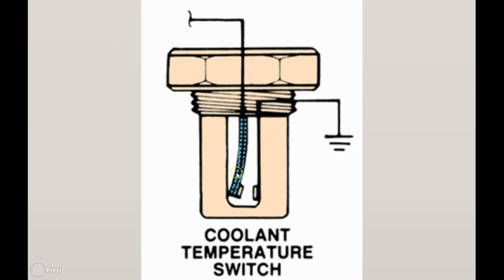And in this case, what it would do is it would bend over and make contact between these two things right here. And then current would flow in, down this bimetallic strip, over and down, and it would slide over, contacting here, and that goes out to a ground, very likely turning on an overheating switch of some sort.